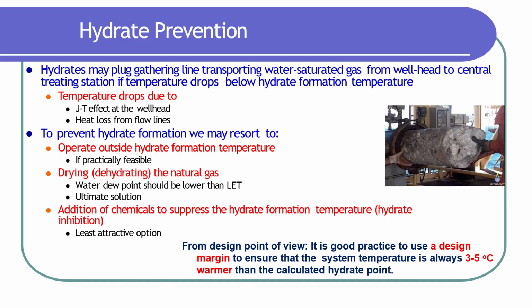obtain these data using graphical solution or using empirical formula based on the specific gravity of the gas that you are dealing with. And we have seen several mathematical formulas, where it's suitable, for example, to use it in sour gas, and which one is good, for example, for sweet gas.